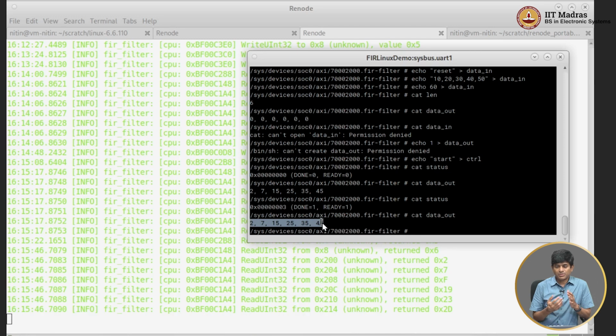So the purpose of all of this was to show, in other words, at this point it should be fairly clear that this is not just a dummy simulation where in Renode I just put in, let's say, a C block or something like that. I actually wrote RTL, Verilog, and when I run each of these commands it is actually directly communicating with that RTL, which in our case has been very nicely converted into a set of C++ functions and compiled into a library, but still at the end of the day it is actually an RTL simulation that is happening out there, okay. And this is the main power of the co-simulation approach.